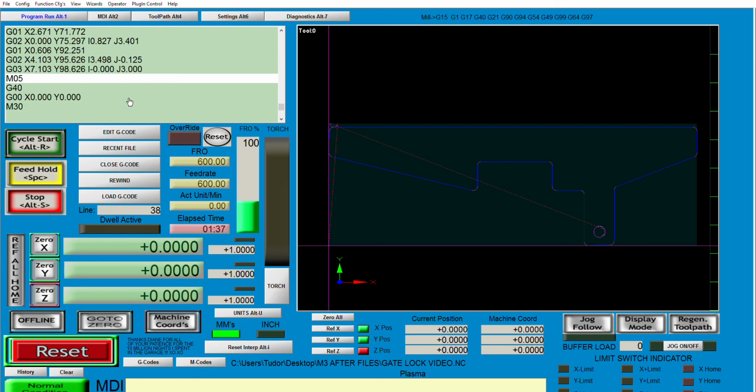So what I do is, let's say you have a lot of remnants. You zero the table where you like, because some of the remnants may not be square, they may be trapezoid, round, whatever. But as long as your cut envelope is within the metal, the only thing you have to do is strip the table and load the table, and hit cycle start each time. It works really well for all the remnants that you have laying around.